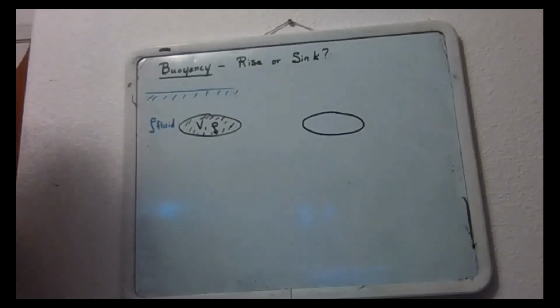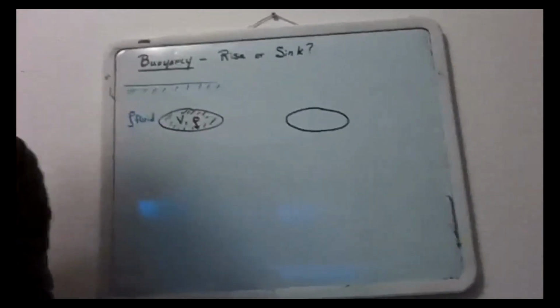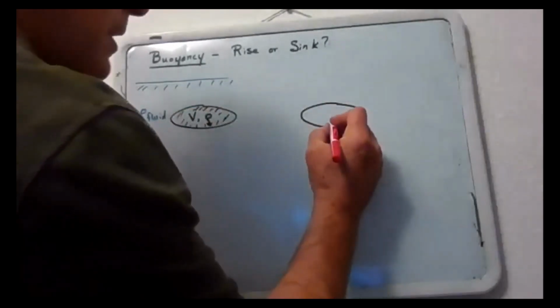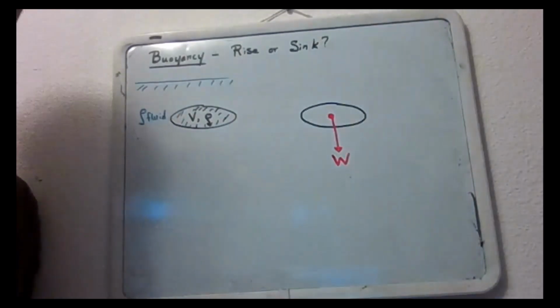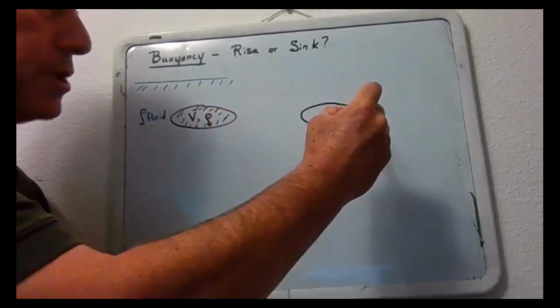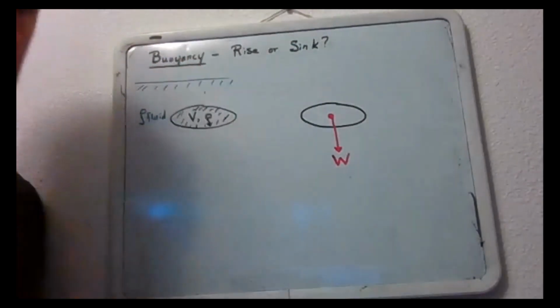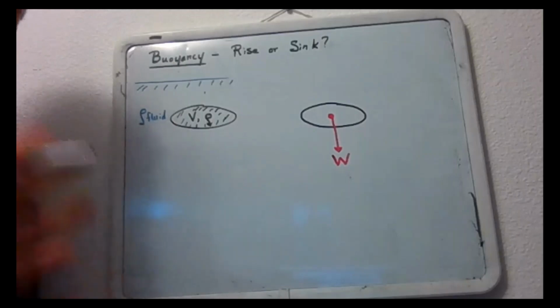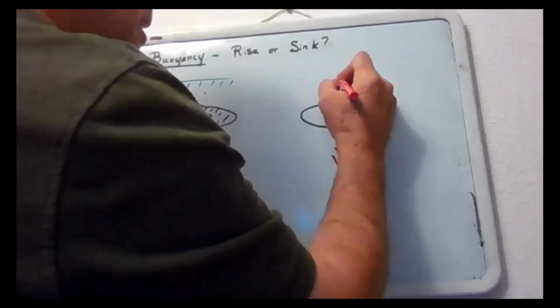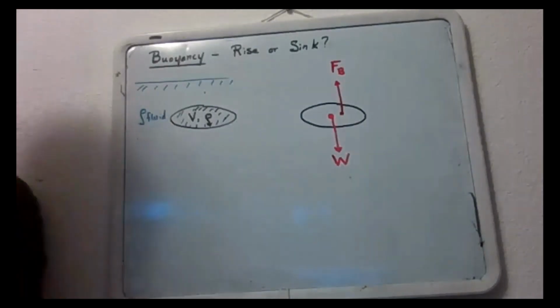Okay, hopefully you got started. In this particular case, we can get it down to two forces. Okay, well, first of all, we're going to be assuming that this object is on Earth, okay? And so one of the forces would be weight. So I can write that down. There would be a force down, which would be equal to its weight. And then in addition, someone might start drawing a bunch of different pressure forces. Pressure force this way over here, pressure force in over to the left, pressure force up from below, pressure force down from below. What do I mean by pressure force? Pressure force of this fluid over here. But what we did last time is we found that for a submerged object, we can break it down into just a single force that we call the buoyant force. So that would be called the buoyant force.